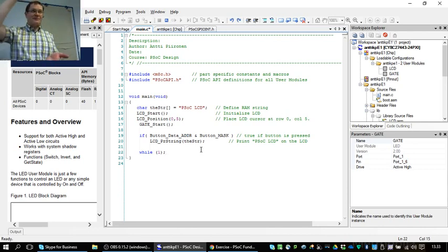Don't let it run into the point that there's nowhere to go, since a processor will keep processing whatever the code you have there. Usually it's basically a block of zeros, which is commonly used as no operation. But after that 4 kilos of no operation, it will go to some boot code again, and it can actually start doing erratic things.